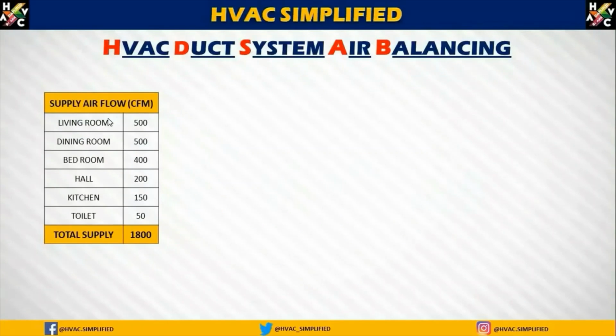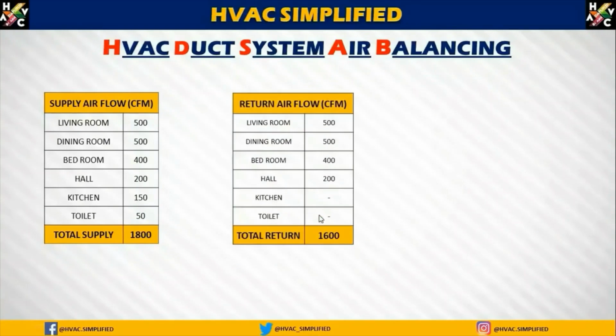Here let us understand with a simple example of a supply airflow, taken from a simple apartment which has a living room, dining room, bedroom, hall, kitchen and toilet. Now on the right hand side you can see the required CFM airflow for each and every zone. So now the total of all becomes 1800 CFM.